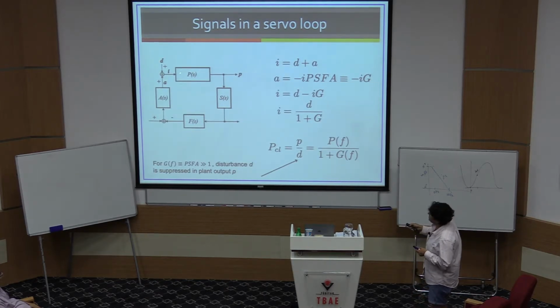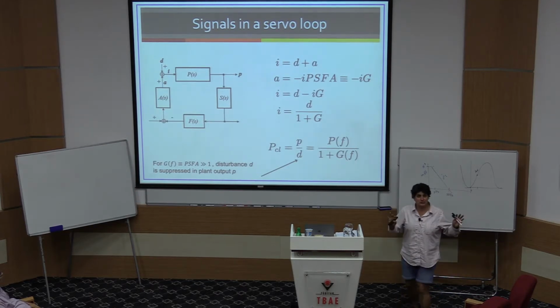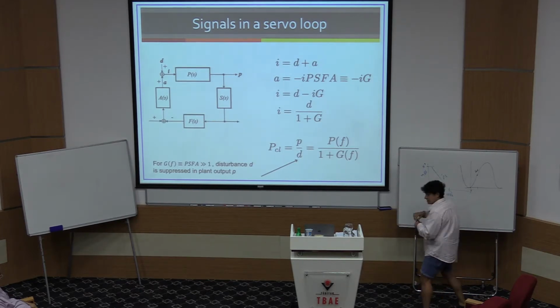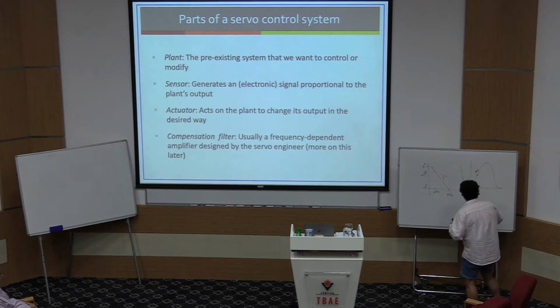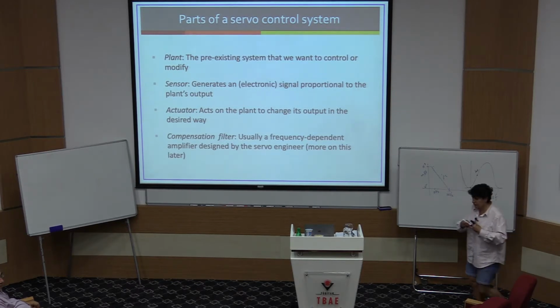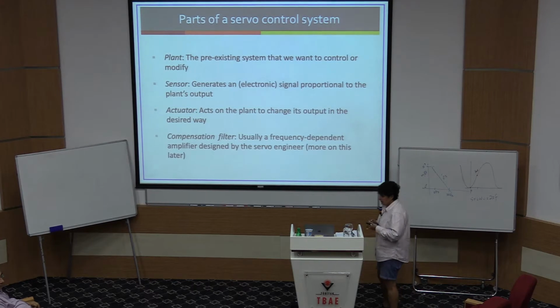And then what we do is, now remember I told you another beauty of working in the frequency domain is that you can just multiply rather than convolving. S in this case, I'm sorry to mix units on you, this is engineering units, but you don't have to worry about it. Just think of S as imaginary times omega, which is frequency, so it's just imaginary times 2 pi frequency, okay? So just think of it as frequency, all right?